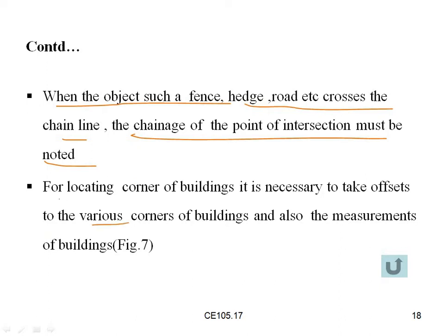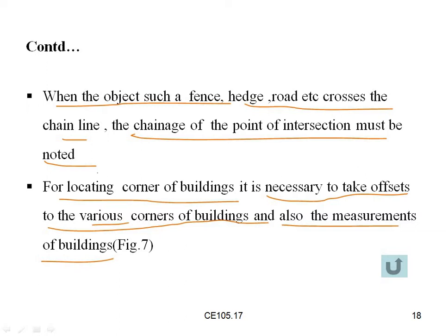For locating corners of buildings, it is necessary to take offsets to the various corners of buildings and also the measurements of buildings.